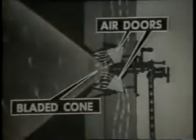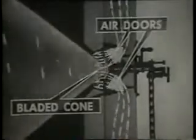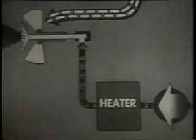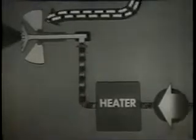In burners with mechanical atomizers of the pressure type, the sprayer plate atomizes the oil, heated and under pressure. The register gives the blast of air from the blower a rotating motion and mixes the air with the oil. You vary the pressure on the oil supply line to control the amount of oil entering the furnace.